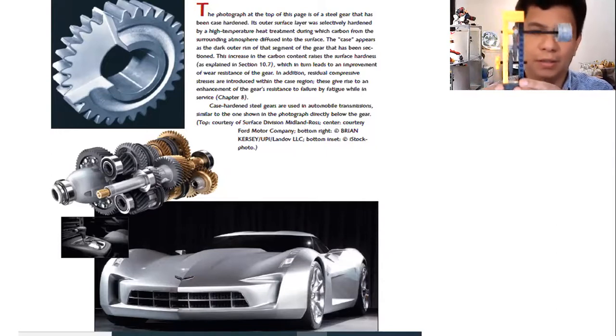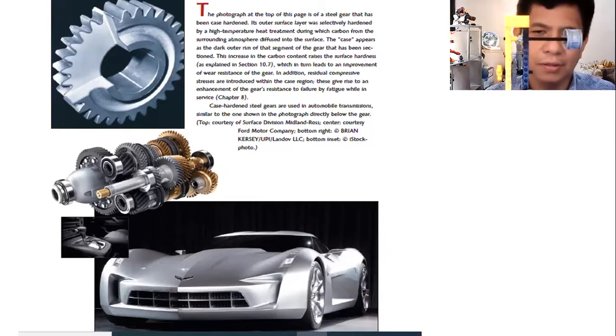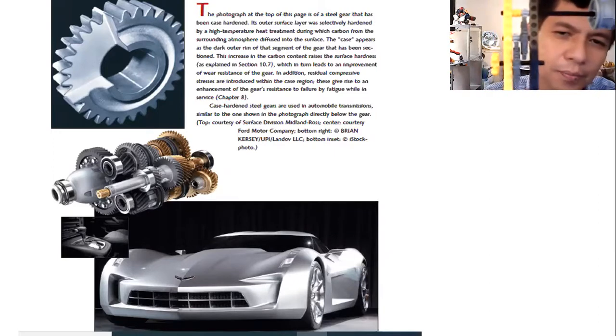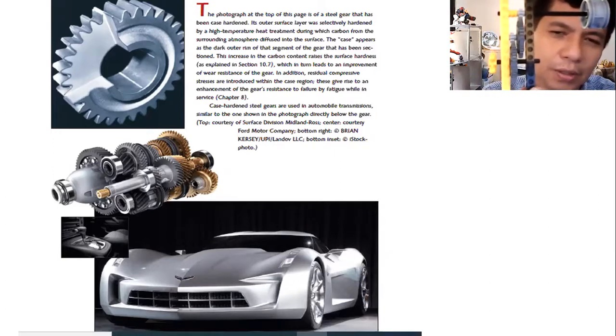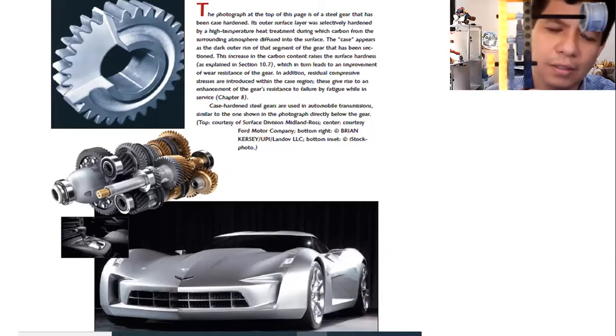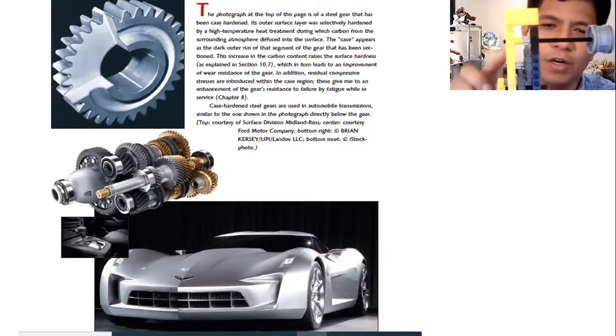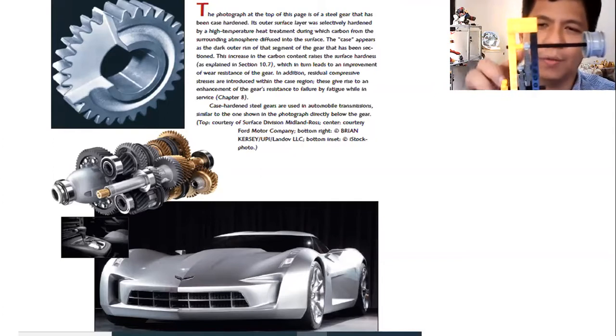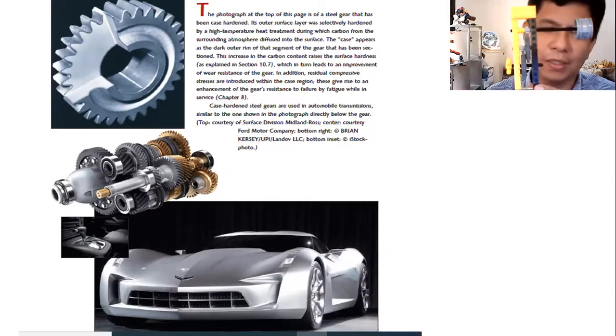This is a mixer, no? So the larger gear has 40 teeth. Tapos the smaller gear, I hope you can see the smaller teeth. The smaller gear has 8 teeth. This is 40. So 40 divided by 8, that's 5. No? Tapos dalawang pairs ng gear.